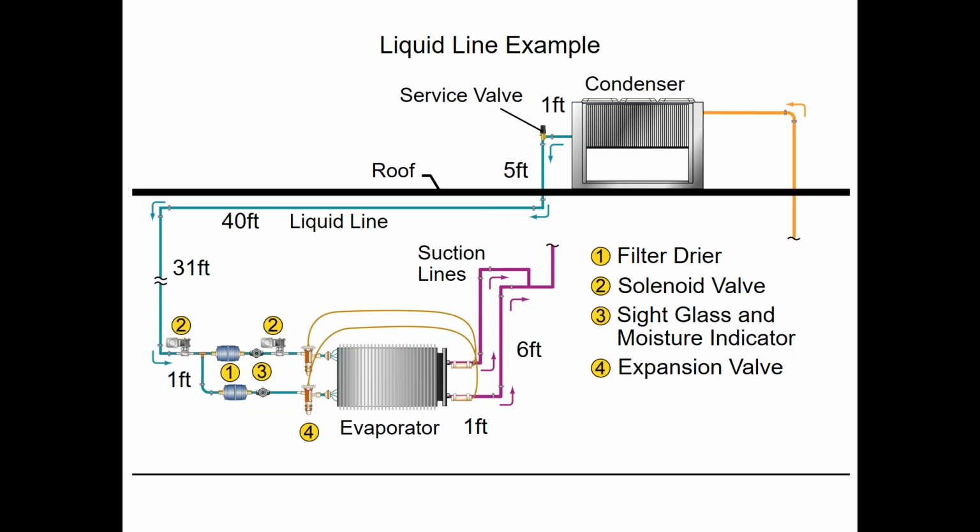But if you've got long piping on an HXA, which is air cooled, you can carry that oil out and have problems. The machine's smart enough to know it doesn't have oil because it's got an oil level sensor, or switch, if you will. It's also looking at oil pressures. It knows if it's low on oil and it won't start.